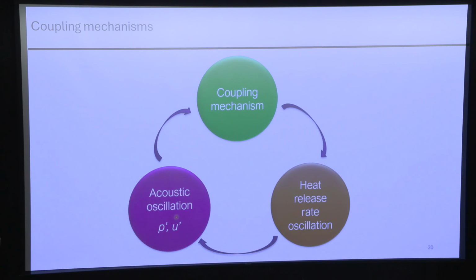And so what you typically have instead is something called a coupling mechanism as the mediator in between. So you have your same acoustic oscillation. That acoustic oscillation causes another oscillation, and then that other oscillation drives the heat release rate oscillation, and then you get the compression expansion work that feeds back into the acoustic oscillation.